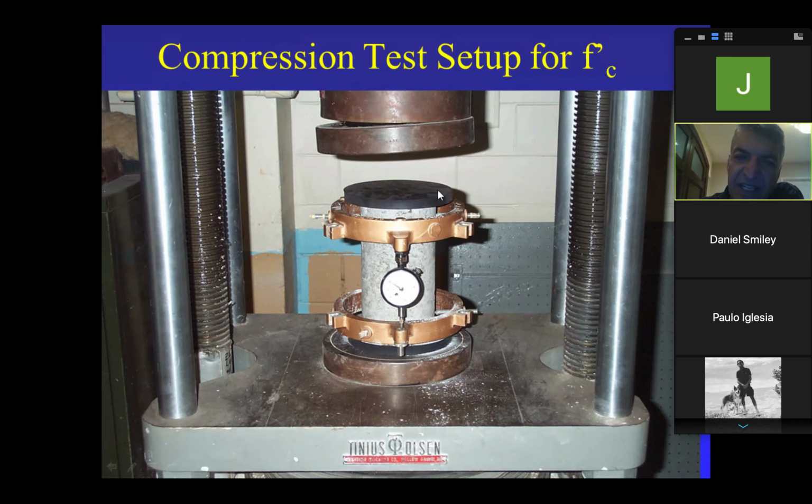If you look at the top of the cylinder, the diameter is 6 inches. So what's the area? It is pi r squared. The r is 3 inches, squared, 9 times pi. That is the area. So you take that force from the machine divided by the area, and that is going to give you the stress. Stress equals force over area.